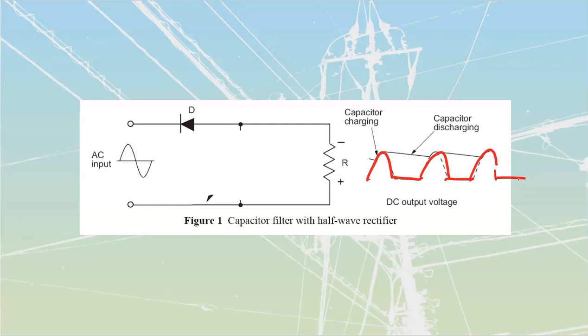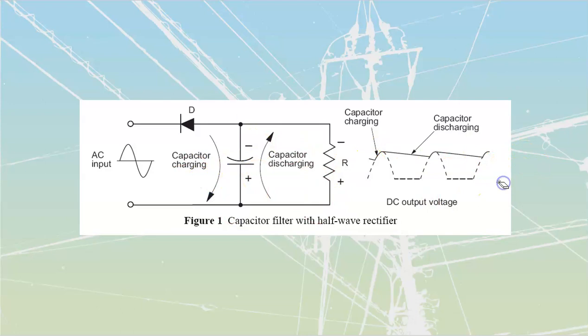What this does is it provides a rather erratic operation for any type of load, because it's going to get a burst of power and then nothing. It kind of has to coast its way through, and get a burst of power and then nothing, and coast its way through. It can be really hard on equipment, and it can lead to, once again, erratic operations on those pieces of equipment. What we end up doing is placing a cap across there.